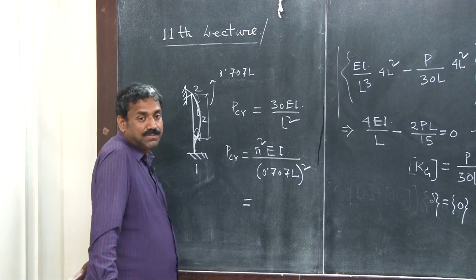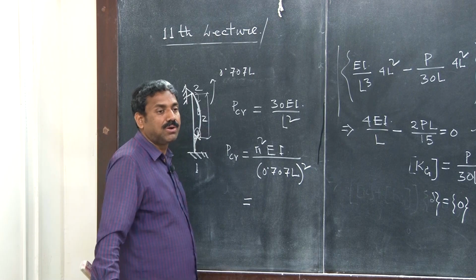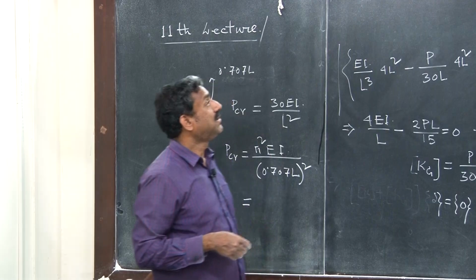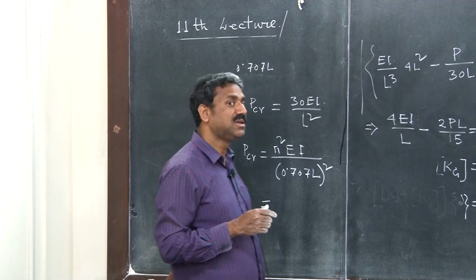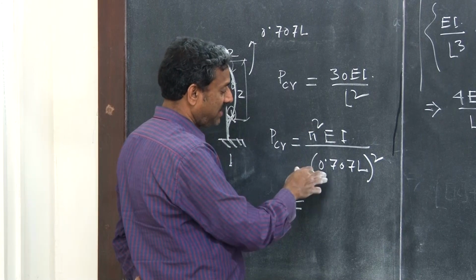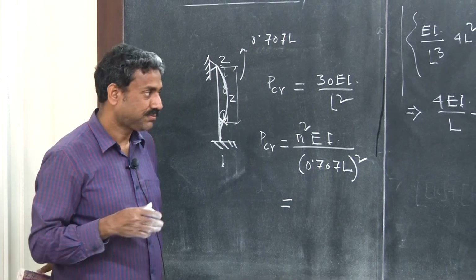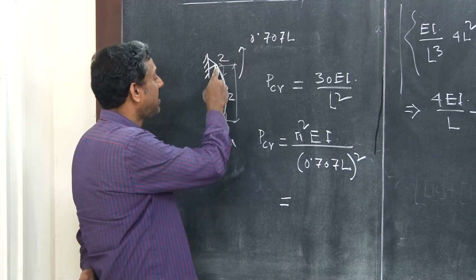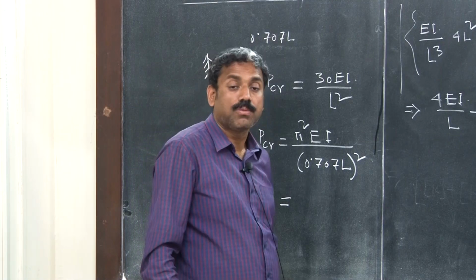And the second thing is that finite element makes the structure stiffer. Because in displacement finite element formulation, you are assuming the displacement field, so you are constraining your structure to deform in some way. That makes the structure stiffer. Displacement finite element always makes the structure stiffer. The error can be reduced by having higher and higher discretization. You can have 2 elements, 3 elements, and thereby capture higher and higher modes, right. So you can do more problems, okay.